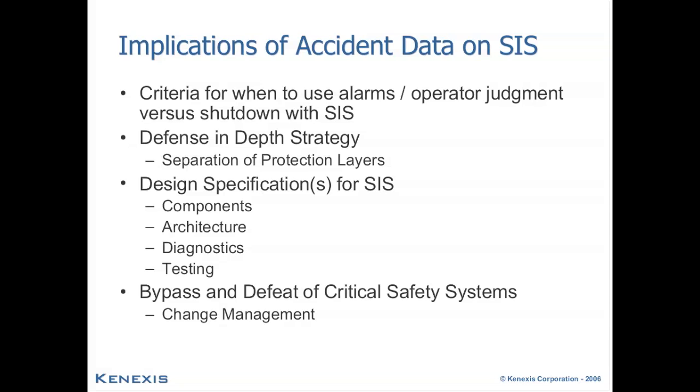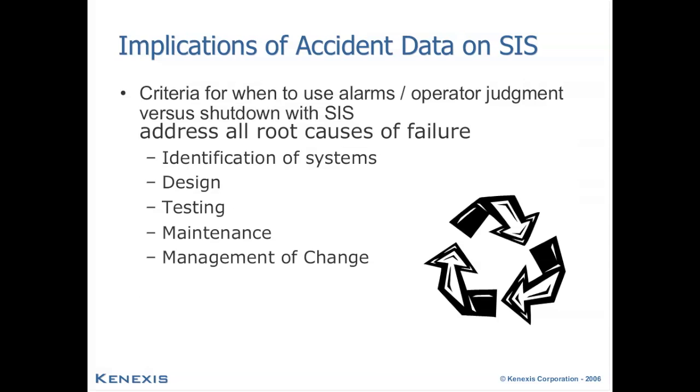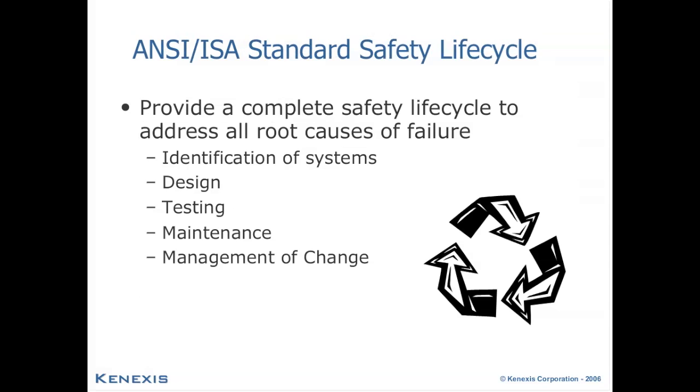Too often we see safety systems that are well designed, well intentioned, but are all too easily bypassed, and are bypassed in an effort by an operator to maintain control of the process in the face of already out-of-control process conditions. So those are some of the implications of the accident data and what it might mean to proper design of a safety instrumented system.